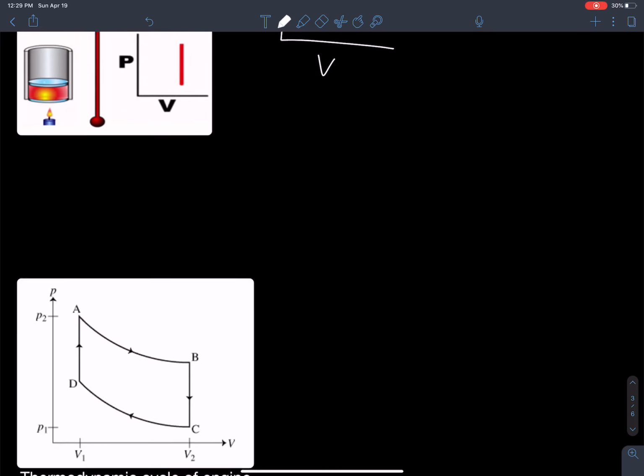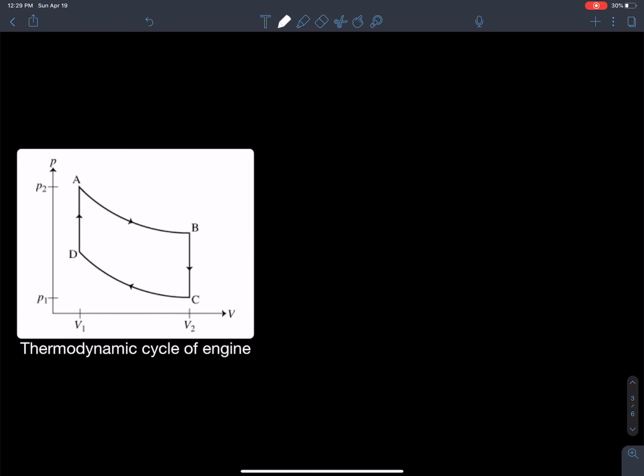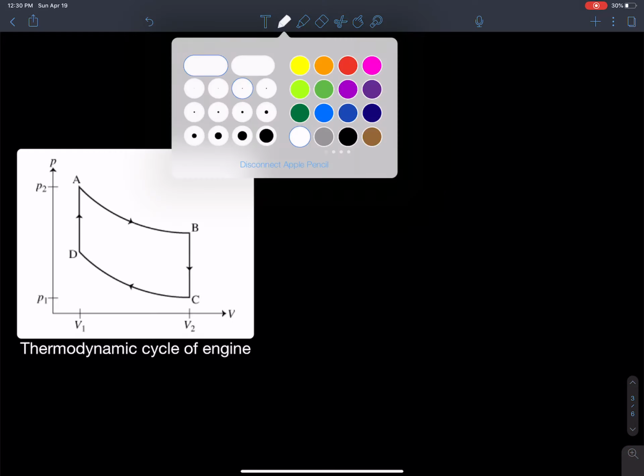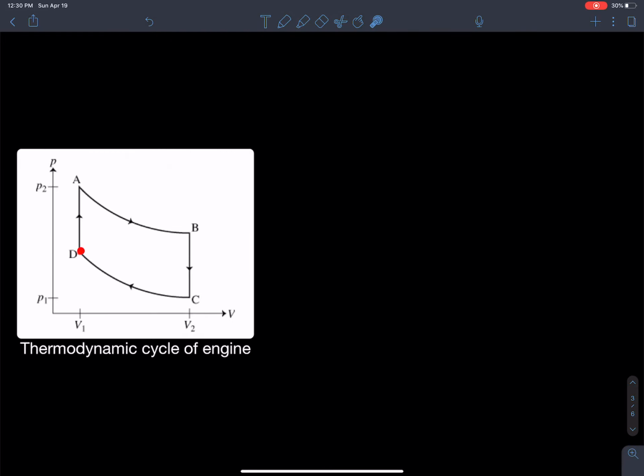Okay? All right, and here's an example of a thermodynamic cycle. So if I started here, and I ignited a gas inside and it quickly changed isotherms and went up over here, what I'm doing is I'm loading the system with more potential for work. If it was just isobaric over here, like I showed you before, that area under the curve there would be the only amount of work that I could do. But here, with an explosion and then an isothermal expansion, I have increased the area under that curve. I can generate more work under that situation if I do an explosion inside of a piston, okay?